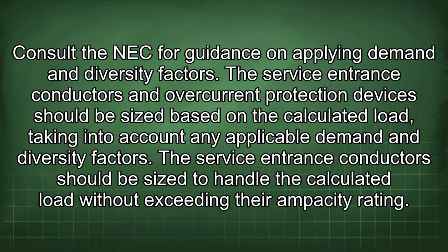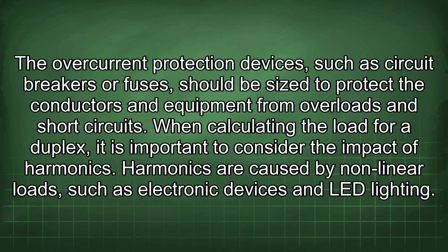The service entrance conductors should be sized to handle the calculated load without exceeding their ampacity rating. The overcurrent protection devices, such as circuit breakers or fuses, should be sized to protect the conductors and equipment from overloads and short circuits.